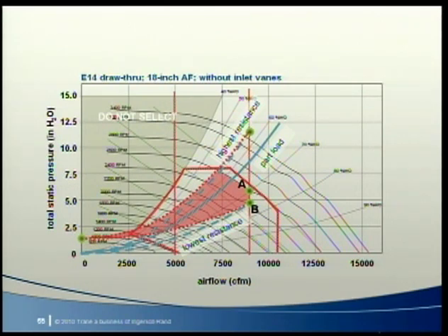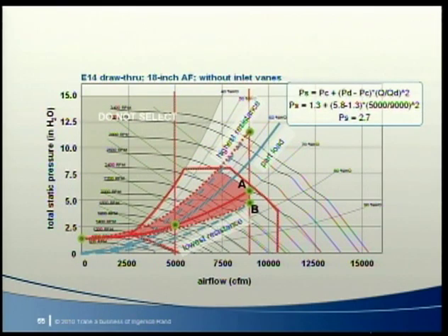Although we could calculate the predicted operating point more accurately, like we showed in your handout, we usually keep things simple by assuming that the fan operates at the intersection of the system curve and the design VAV modulation curve defined by this equation. In this example, we conclude that the fan operates at about 1,600 RPM, delivering 5,000 CFM at about 2.7 inches. So this fan selection works fine, as long as the airflow is more than about 30% of design. The fan doesn't cross the surge line.